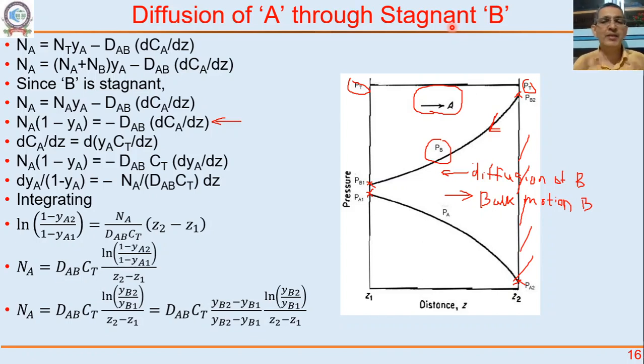In reality B is diffusing from right to left by molecular diffusion, but it is taken by A along with it by the bulk motion because of the net transfer of A. These two processes occur at exactly the same rate, because B is not reacting, so there is no net transfer of B. That's why an outside observer sees B as stagnant.